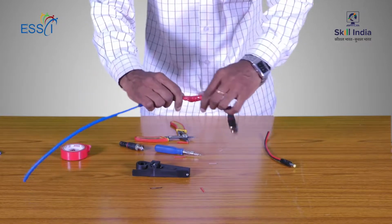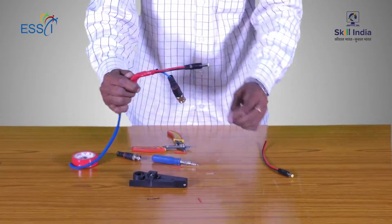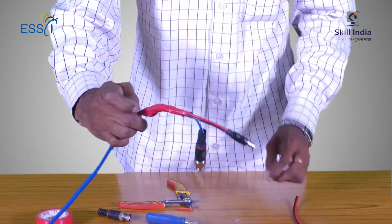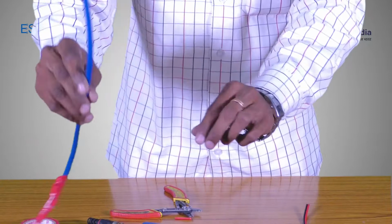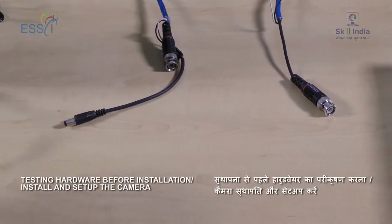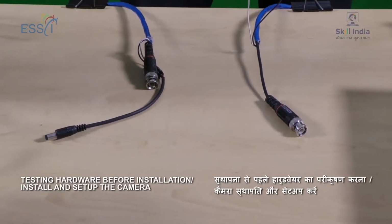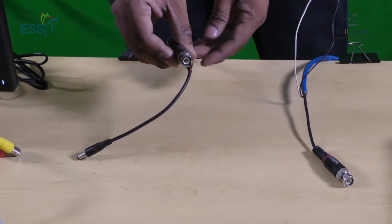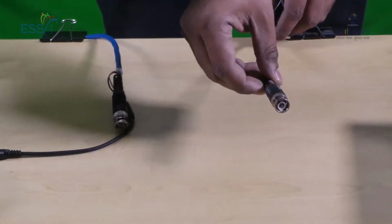This is used to supply power to the CCTV camera. This is how we connect the connectors to the CCTV cable, and we repeat the same process for the other end of the cable. Once the BNC is connected to both the ends, the cable looks like this. For the camera end, the cable looks like this, and for the DVR end, the cable looks like this.